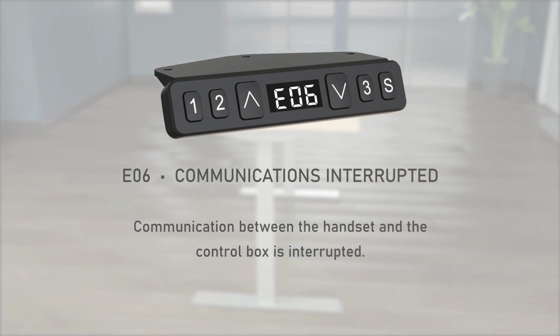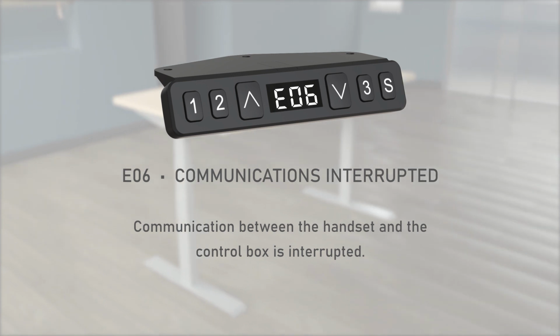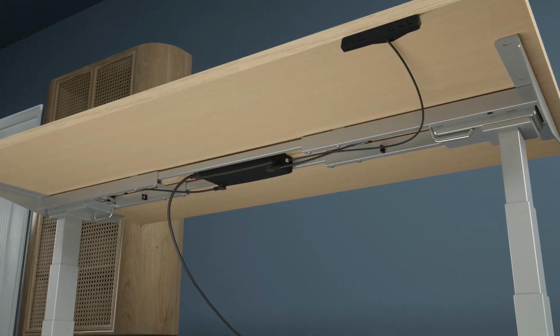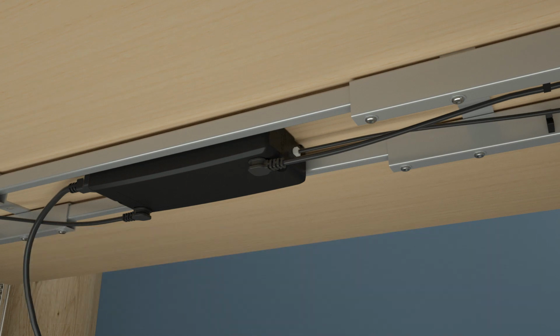E06, communication interrupted. Communication between the handset and the control box is interrupted. Disconnect and reinstall the handset cable to the control box, assuring that the end connector is fully seated and secured with the built-in connector clip.